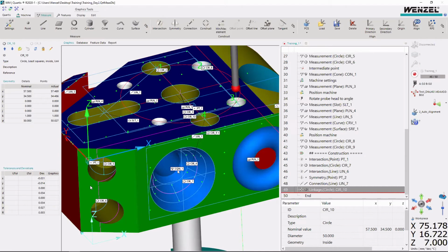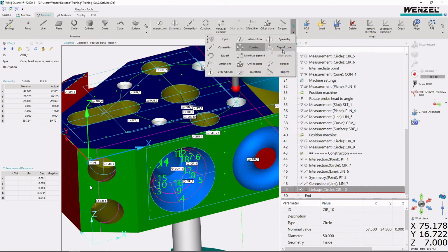So double click on it, and then this cone 1 is here now. And then now the top of the cone is available for me to click. So if you find that the top of the cone is unavailable, you just need to check the left element window. Is your cone 1 inserted there? Okay, if not, just bring it in.